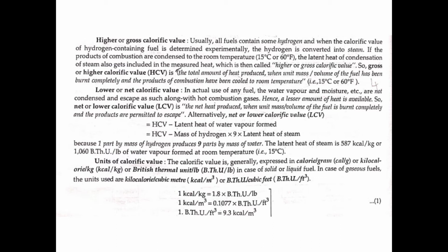The second one is the lower or net calorific value. It is the net heat produced when a unit mass or volume of the fuel is burned completely and the products are permitted to escape. Okay. Lower calorific value can be calculated as higher or gross calorific value minus the latent heat of water vapor formed.